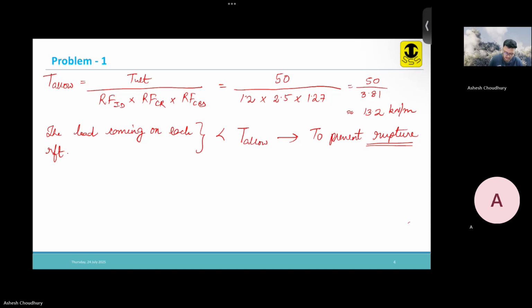Now, the load coming onto each level is nothing but the spacing S_V times the horizontal pressure. In yesterday's class we had written it as K times sigma V times S_V, and K times sigma V is nothing but the horizontal pressure we have already determined.